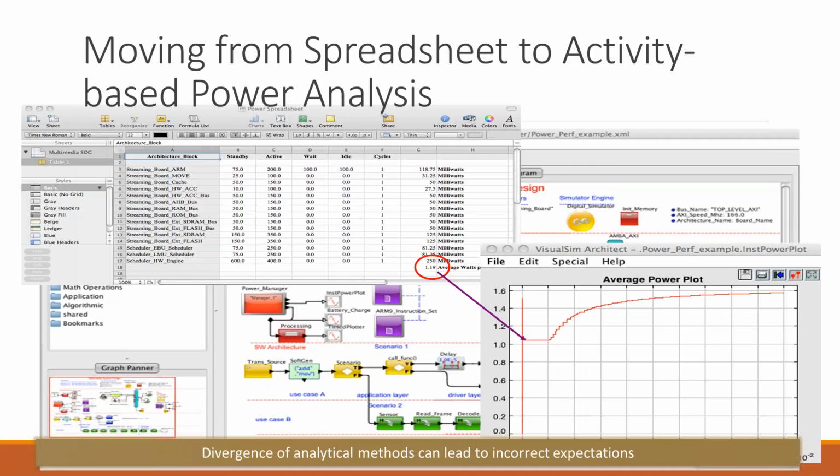In today's design, most times when you look at the power generation or the power storage, you're spending all your effort trying to create Excel spreadsheets that give you certain information about the power. What that means is that it's giving you a very average term for the power. So for example, when we started off, this was the starting point in that model that you saw for the power consumption, which kind of matched the average power you generate. So you take all these numbers, divide by 4, and you get an average number. That's kind of what you use for every one of the use cases. But here, because of the dynamic nature, things get turned on, turned off, and the power consumption actually changes. The power profile completely changes.